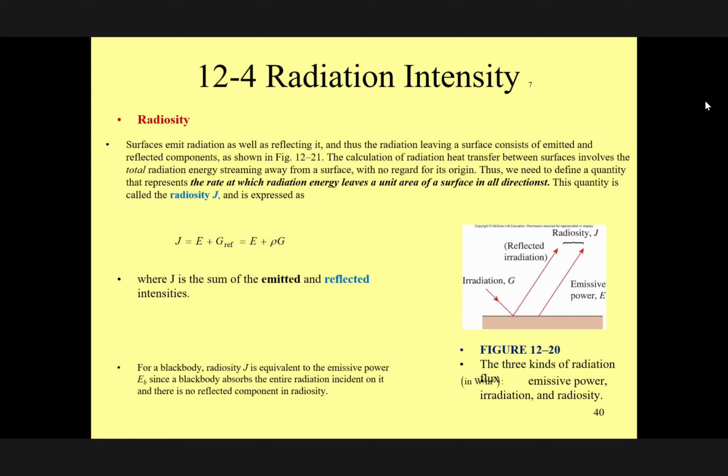You agree? Yeah. We have to go back and slowly bring in the information that we have. We define a black body as a body that absorbs all the energy. It means absorptivity is equal to 1, alpha equals 1. Remember we mentioned alpha plus rho plus tau is equal to 1. Therefore, no transmission, no reflection, and in the case of the black body, J equals this one. This term is equal to 0. Good. Let's go back to the problem that we had before.